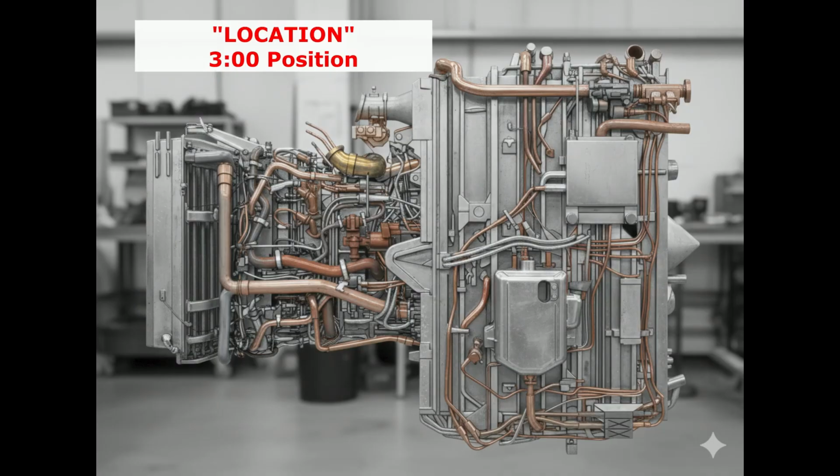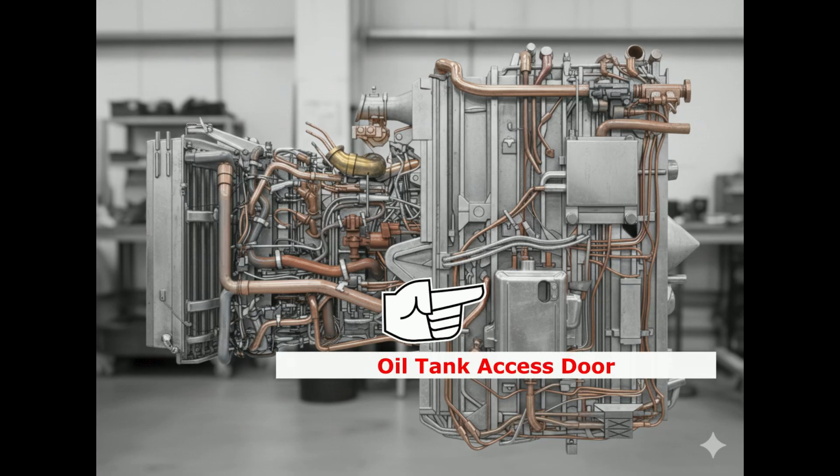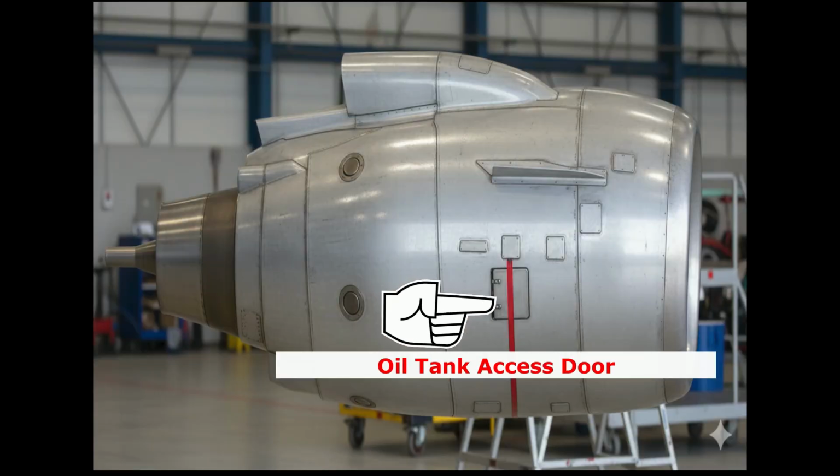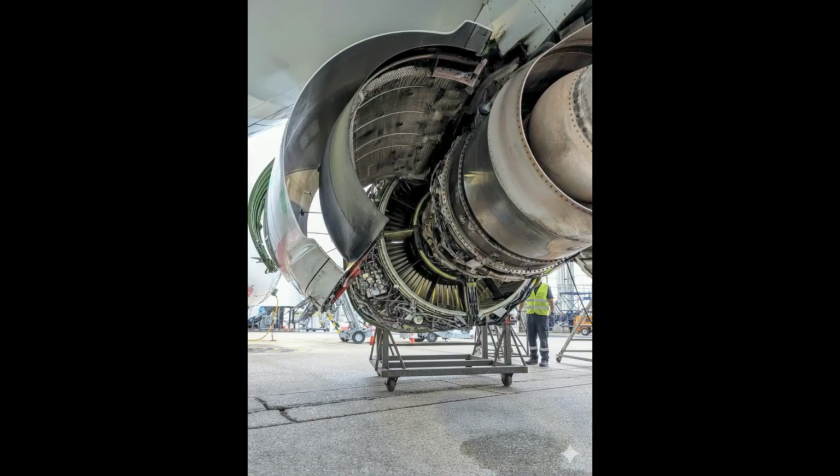Location. When viewed from the rear of the CFM56 engine, the oil tank is positioned on the fan case at the 3 o'clock position. While the engine is installed on the aircraft, oil level checks and filling procedures can be performed through a small access door. This access door is located on the side of the engine fan cowling. For full access to the oil tank and its associated components, the right-hand RH fan cowl can be opened.